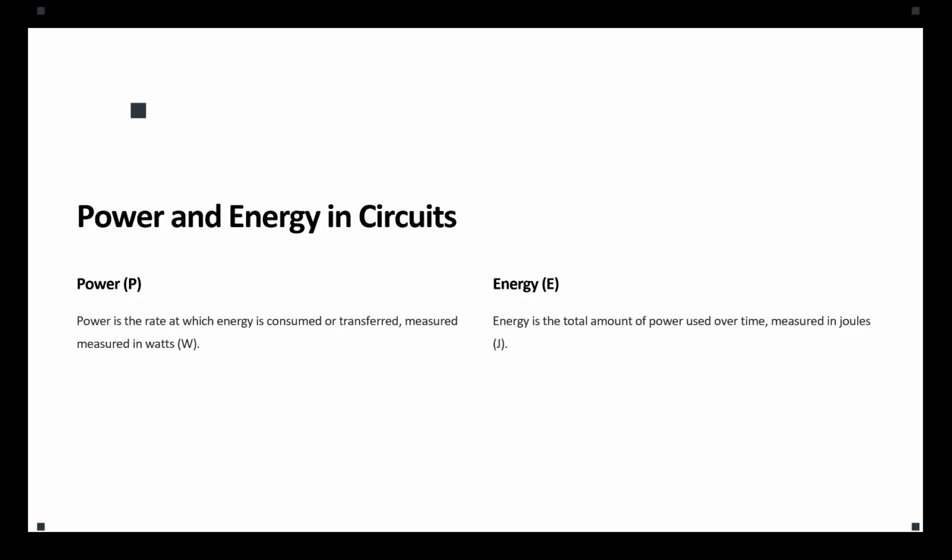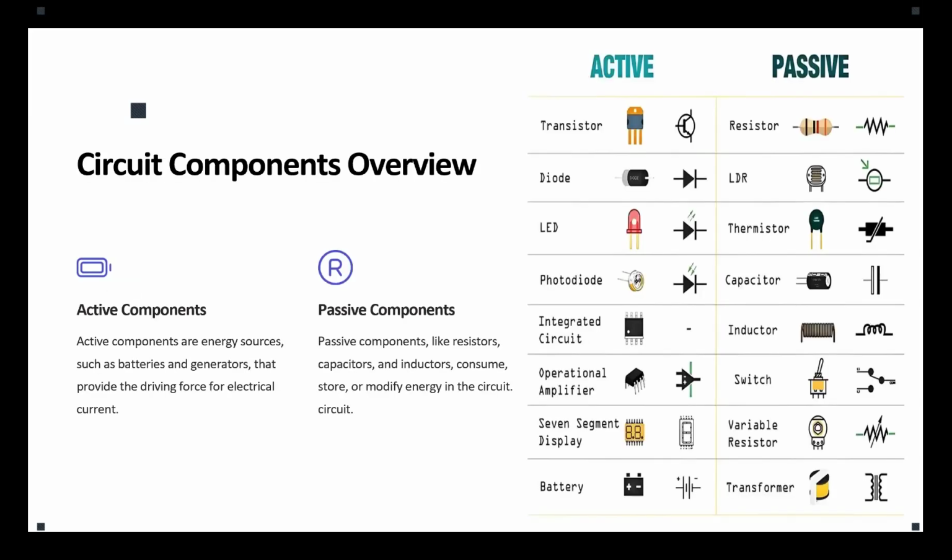Now we have a quarter of a watt resistor in the lab, we have a half a watt, 0.5 watt resistor in the lab, or we have also a load resistor which can tolerate more than that. When you want to tune your DC source, you need to pay attention. I have a quarter watt, 0.25 watt resistor. So whatever voltage that I apply, which would result in a certain amount of current, the multiplication of them should not exceed that capacity of the resistor. Does that make sense? So this is why we pay attention to the power all the time. Otherwise, you're going to burn your circuit.